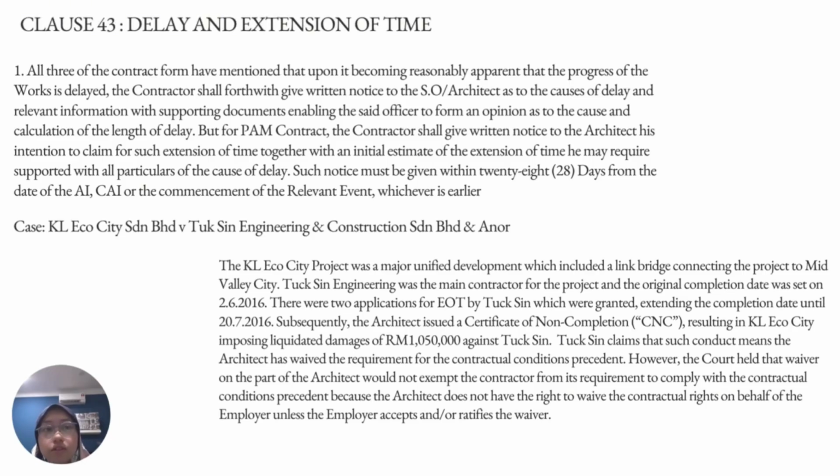Next, clause 43, delay and extension of time. All three of the contract forms have mentioned that once it becomes reasonably apparent that the progress of the work is delayed, the contractor shall forthwith give written notice to the SO or architect as to the causes of delay and relevant information with supporting documents enabling the said officer to form an opinion as to the cause and calculation of the length of the delay.